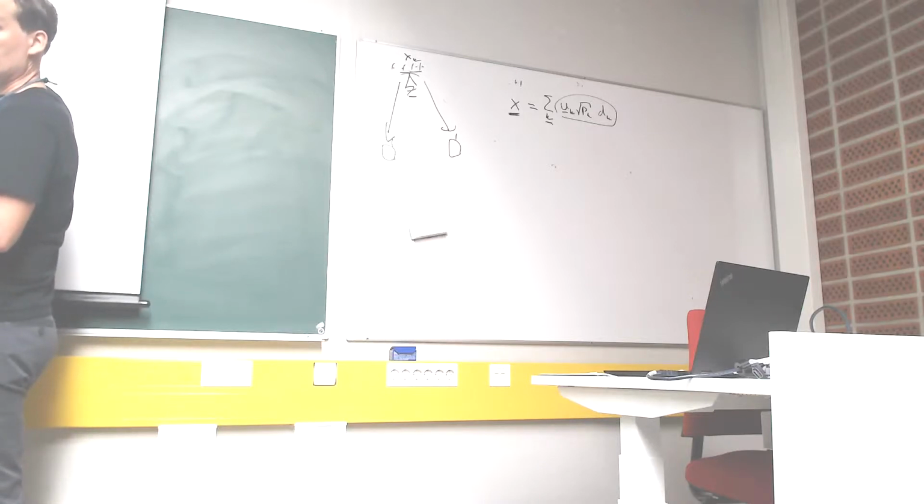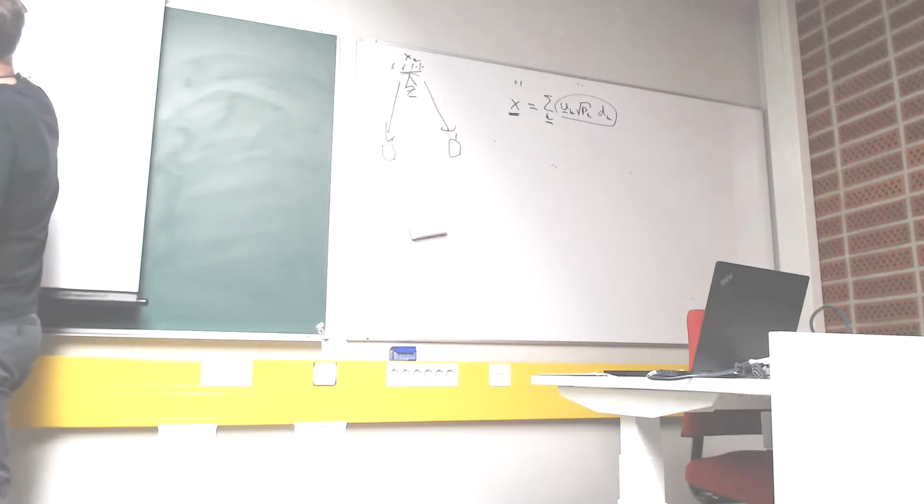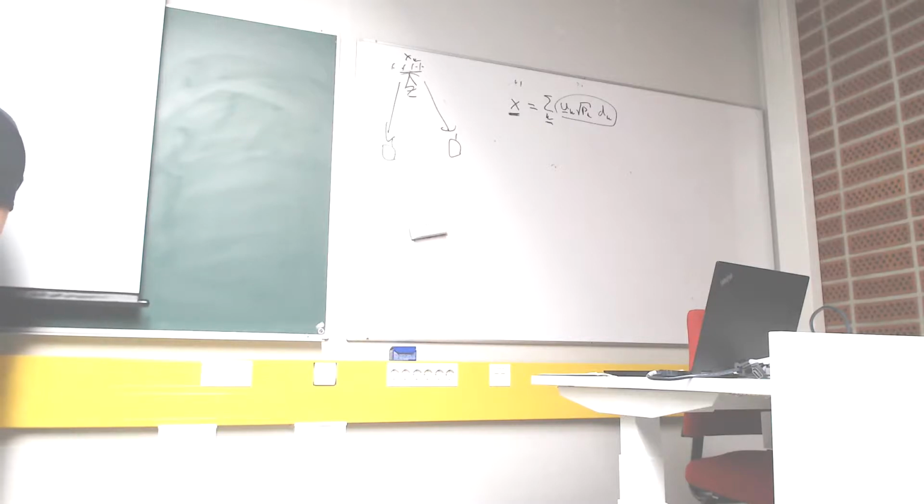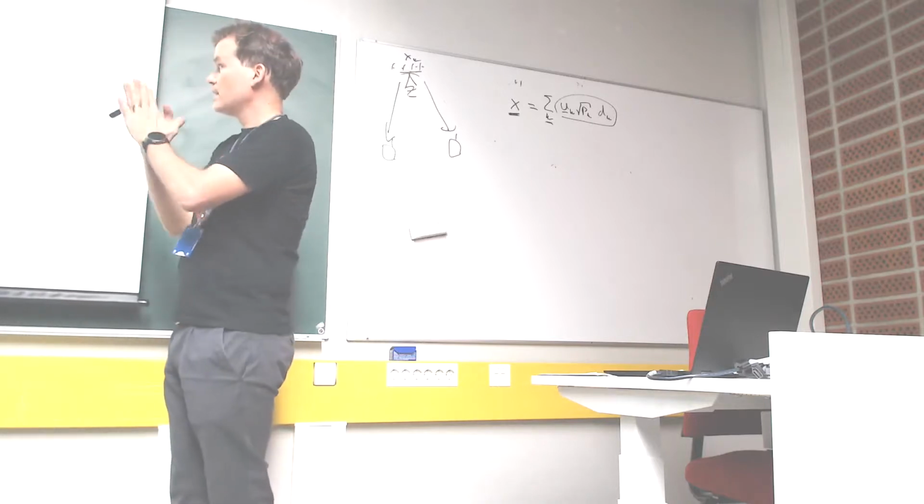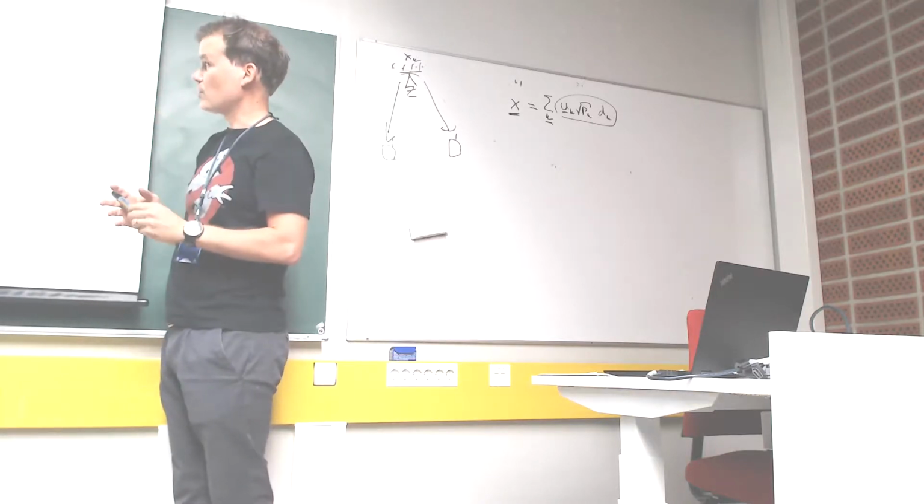If you do zero forcing, you don't care about the noise, you force this to be zero. And that's not a good solution in general, because when you force something to be zero, then this u is optimized just to make this cross product zero, and then you don't have the matched filter. The beamformer is not necessarily matched to the desired component.